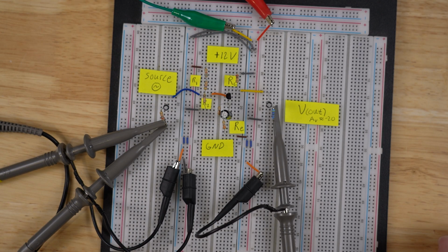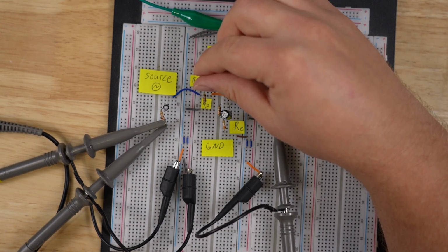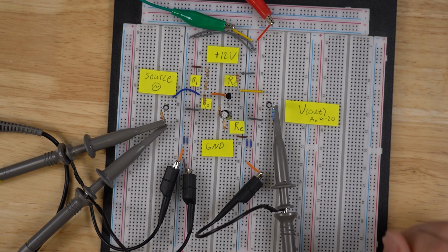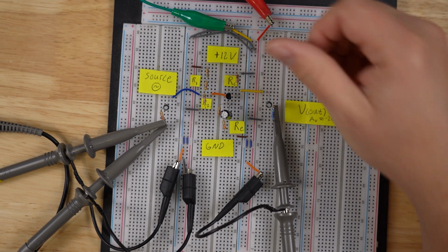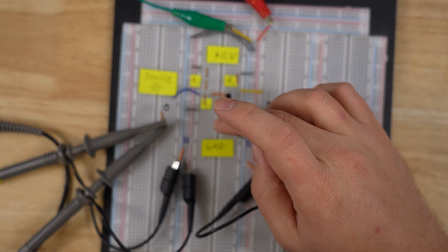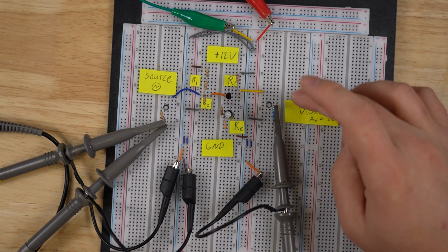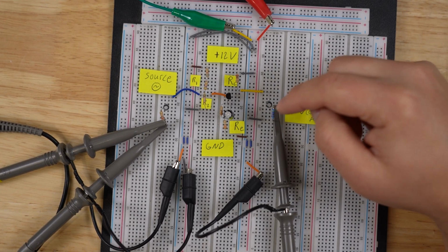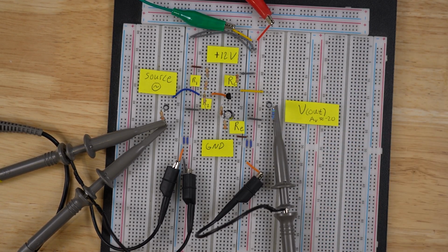I have my coupling capacitor here. I have 2 R1 resistors as we calculated and 1 R2 resistor. Got our RC resistor here, 12 volt DC source, and our RE section with the RE bypass. And then our V out with the load. Now keep in mind, do not sample from the bottom of the load for V out. That is connected to ground, so you'll get 0 and be confused for a little bit.